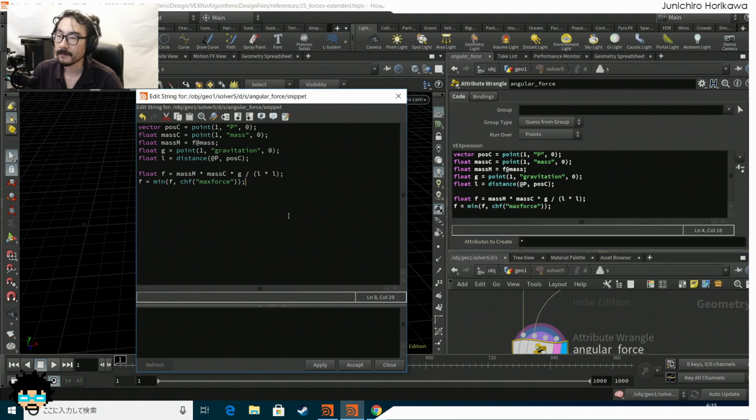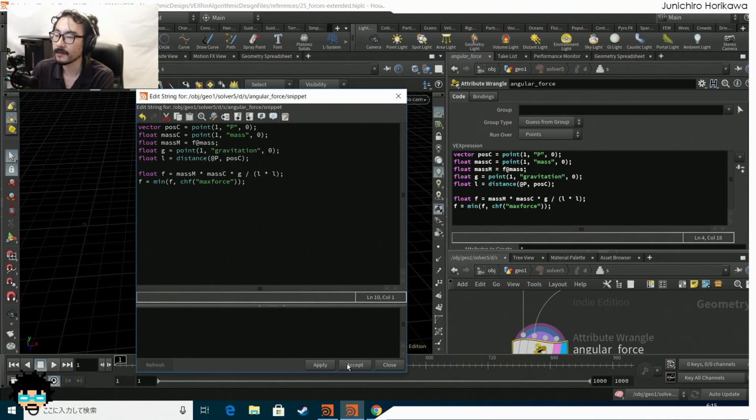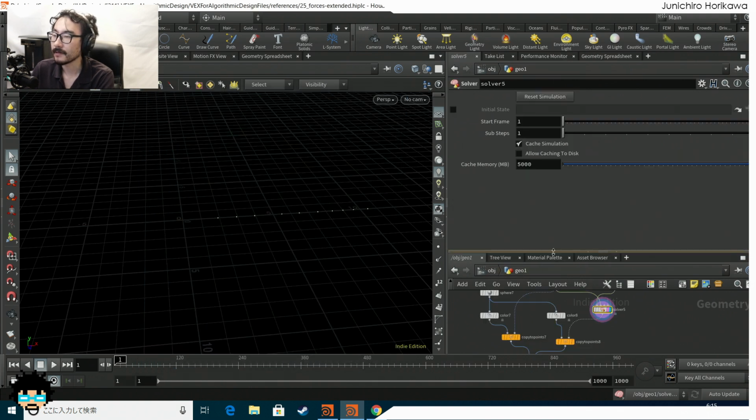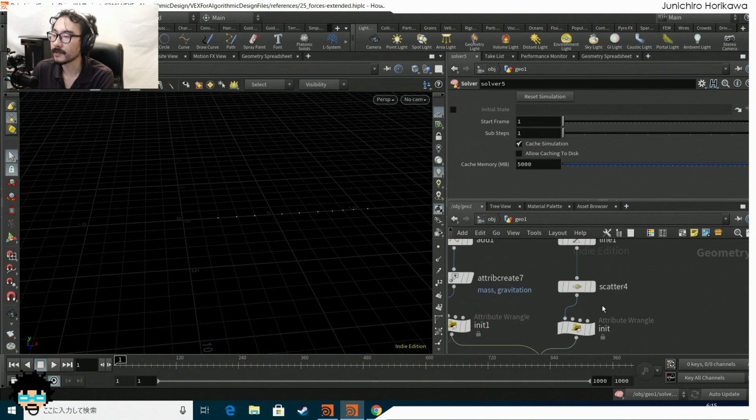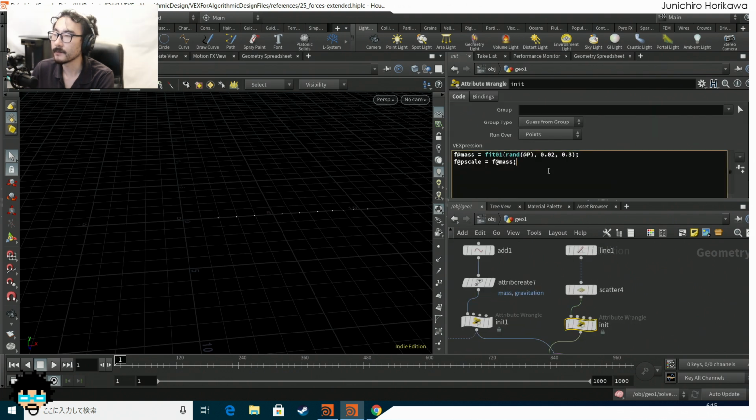Now, after doing this, we could increment the angle attribute, which we haven't created yet. So let's do that first. Let's go back outside for the moving object, which is this point. I'm going to also create an attribute called ang, which is going to be used to rotate the object.